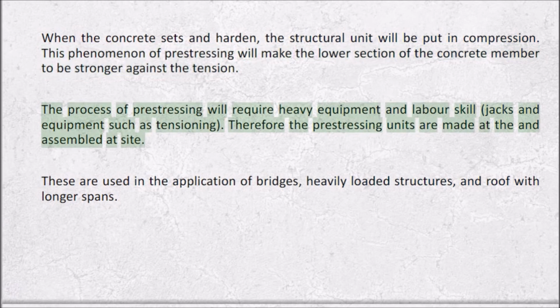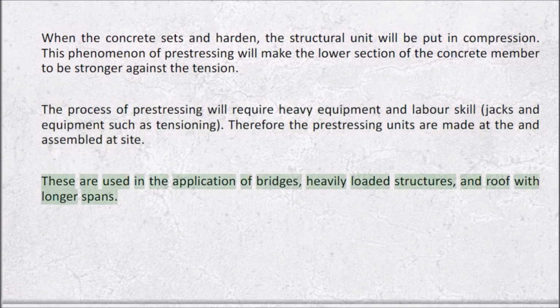The process of pre-stressing requires heavy equipment and skilled labor, such as jacks and tensioning equipment. Therefore the pre-stressed units are made at the factory and assembled at site. These are used in bridges, heavily loaded structures, and roofs with longer spans.